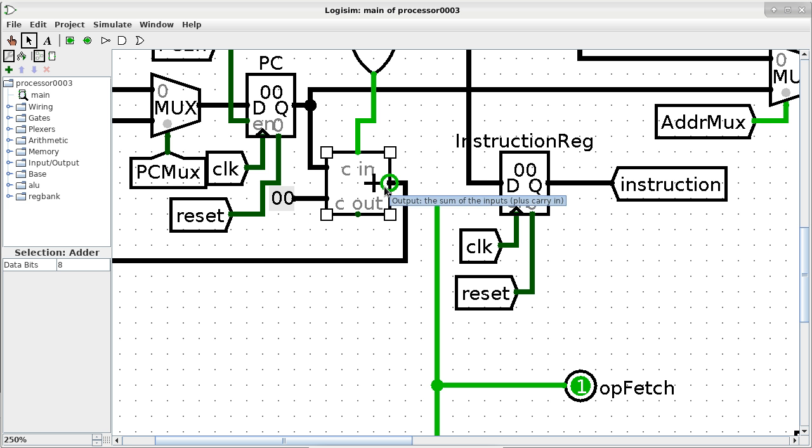Why is there a constant to one of the inputs? Because this adder only has a simple job to perform. Add 1. That's all it needs to do. Day in and day out, that's all it's going to do, just add 1. Do we add 1 or not? That's all it does. It's a part of a circuit that makes a counter. Click counts 1. Click counts 1.